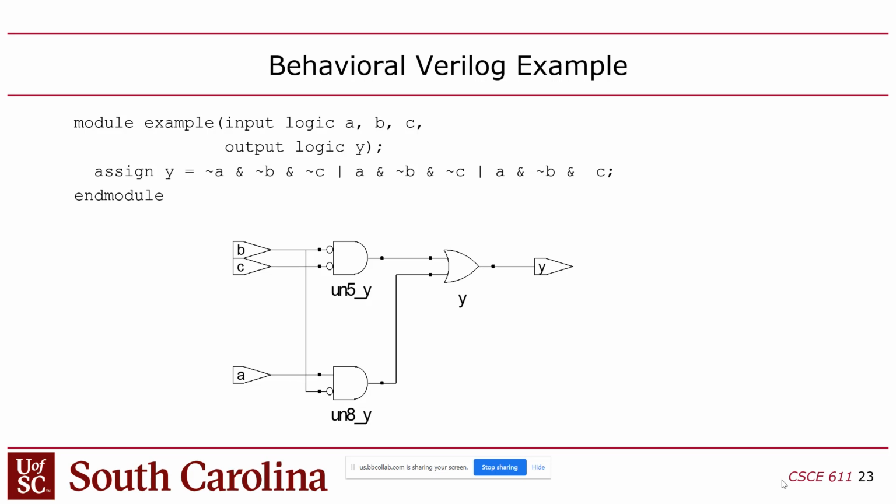Generally speaking, I found that the synthesizer usually doesn't spend a whole lot of time. And when I say that, I base it on how long I have to wait. Like when you compile, usually the synthesis is pretty quick. It goes from that to that fast. Then it goes to put the design on the FPGA, and then you have to wait. That's a harder problem. Figuring out where to put those on the FPGA takes longer.